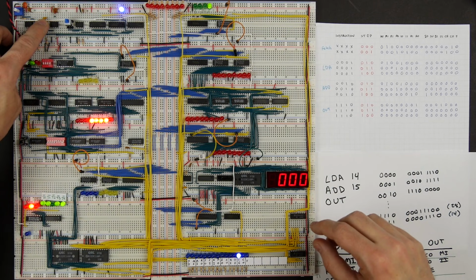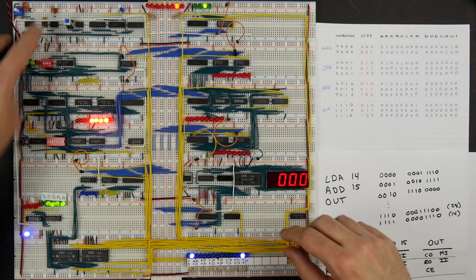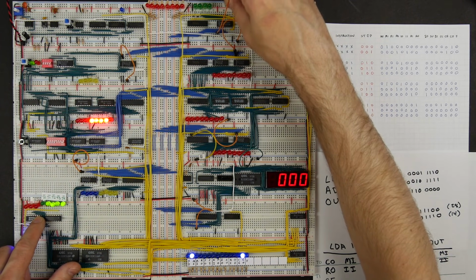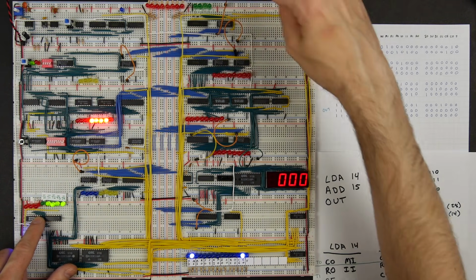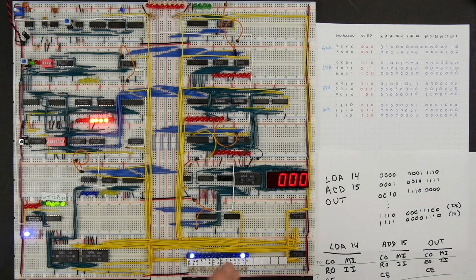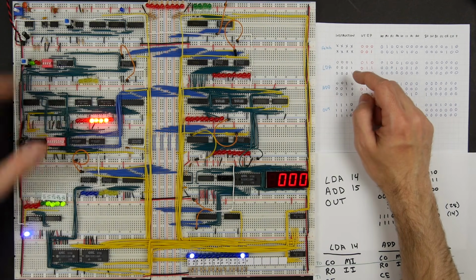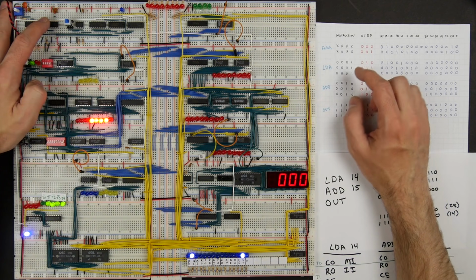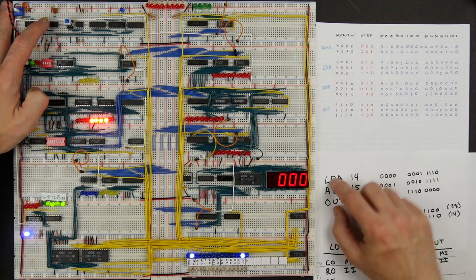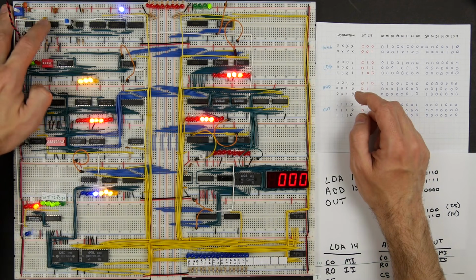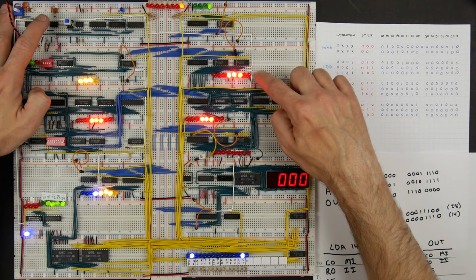Probably just going to have to advance the clock until we get to T0. Okay, there we are. So that's a T0, program counter, make sure that's back at 0. Okay, so we're reset, and I'm actually just going to step through because the place we failed was in loading the output. So let me do the load A and the add. So I'm going to just quickly step through the load A again. So it's the first 5. So that did a load A, and we've got our 28 there.